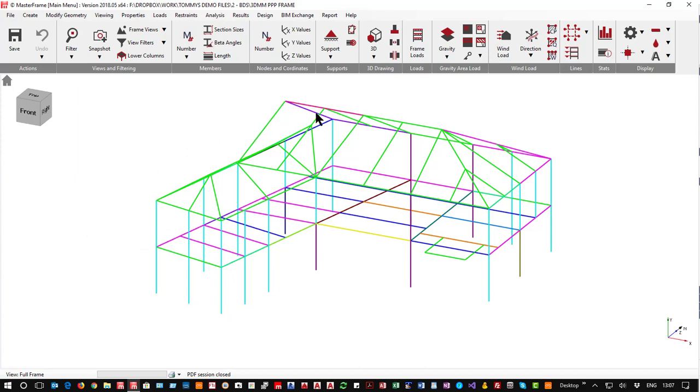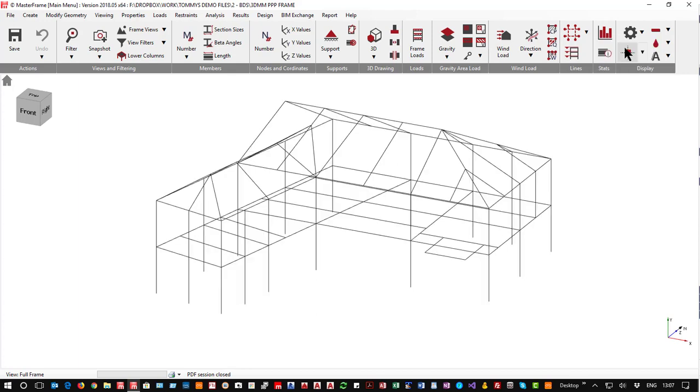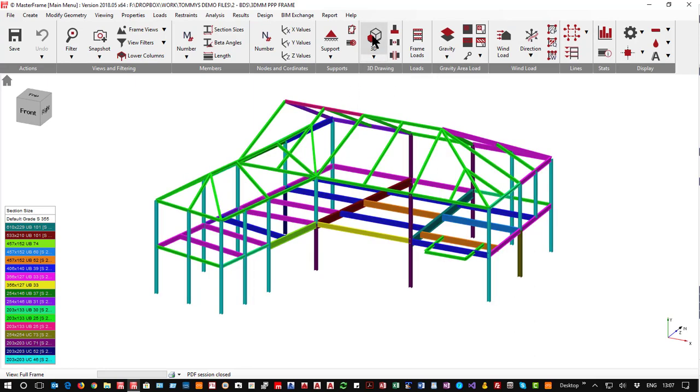And you'll now notice that we're displaying everything in multicolors. And this is where the 3D comes in. The 3D is also telling us whether we want to draw by section. So back to wireframe. And naturally we can come back from thick lines to wire, so it's down to very fine wireframe. So in here you also control the color by section and whether you want a key diagram for section sizes. Likewise, if I leave that there, I can turn on the actual physical sections themselves.